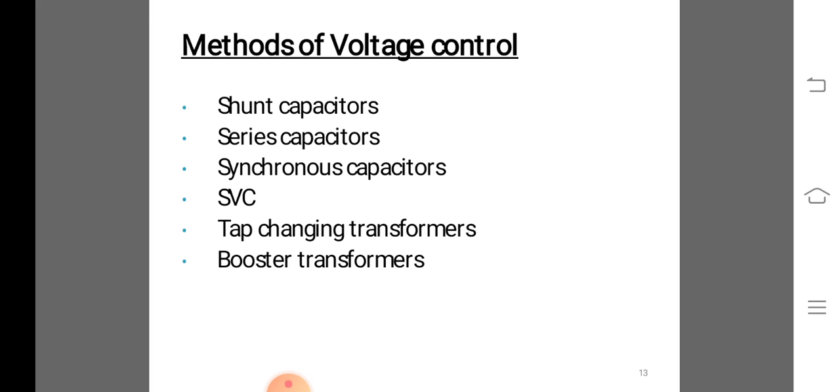The thyristor controlled reactor, that is the TCR, is operated on the low voltage bus in another form of the compensator. The reactor compensator is connected to the secondary of a transformer. With this transformer, the reactive power can be adjusted anywhere between 10% and the rated value. With a capacitor bank provided with steps, the full control range from capacitive to inductive power can be obtained. The reactor's transformer is directly connected to the line so that no circuit breaker is needed.